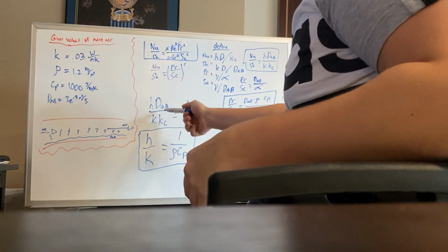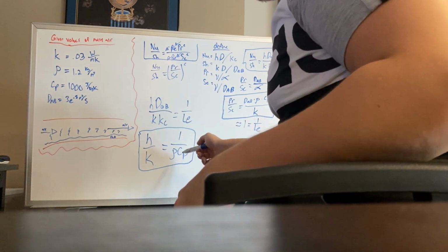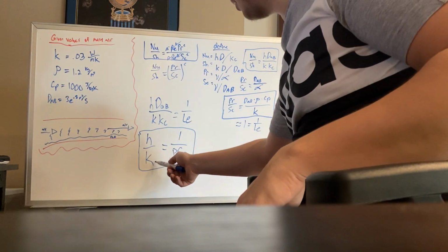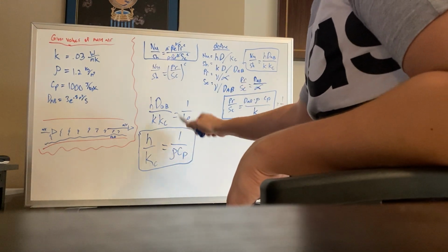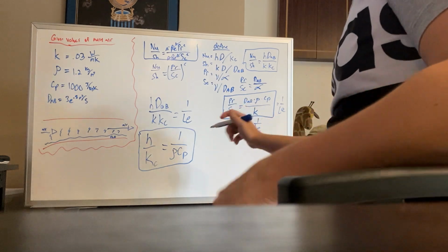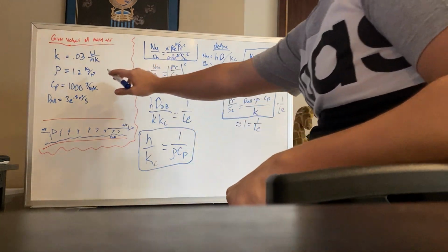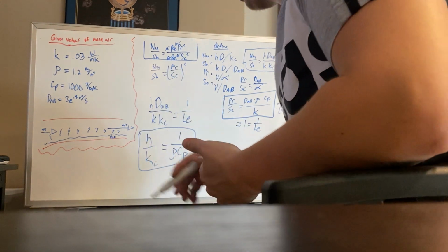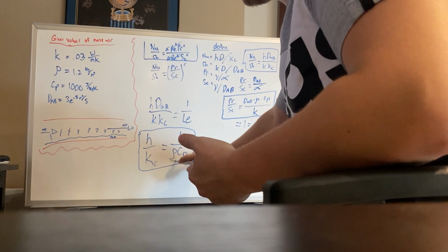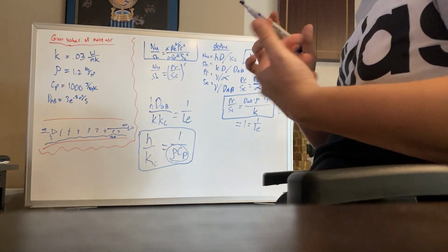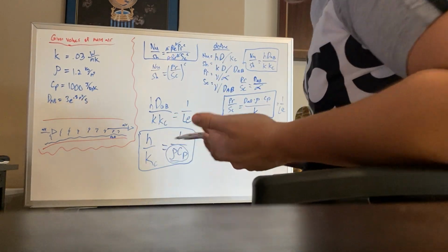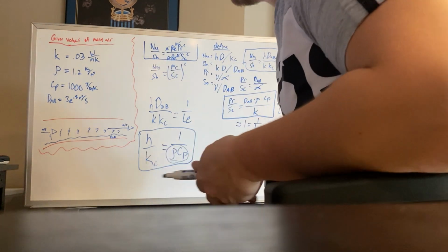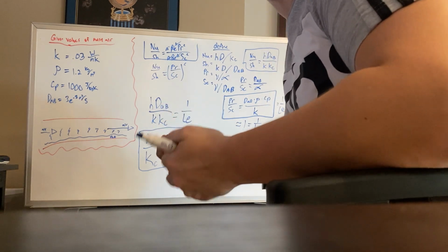And so after we rewrite these and substitute the values for how we want to look at these, we can rewrite it in terms of the heat transfer coefficient over the mass transfer coefficient. And this will be equal to 1 over rho times Cp, which we know is approximately 1 based on the values that we can assume and plug into this equation. That's interesting, and it tells you that the volumetric heat capacity, which is this value right here, is going to be about 1. We can only know this because of the values that we assumed for the Lewis number relation, and we can see that the Lewis relationship is approximately 1.